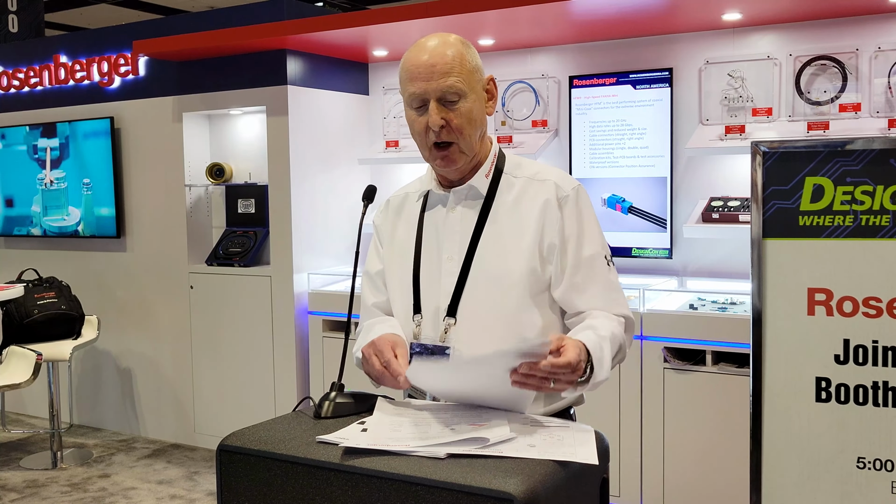Of course, your name, contact information, the connector you're going to use, and whether you're going to place this connector on the surface of the board, or in some cases on the bottom of the board. Some of our connectors are actually on the top of the board, and they go through to the bottom, and vice versa. When we're optimizing a footprint, we'll require the PCB stack up, or what that's going to look like. Your printed circuit board designer will provide that to you, and then you'll have to provide that to us.